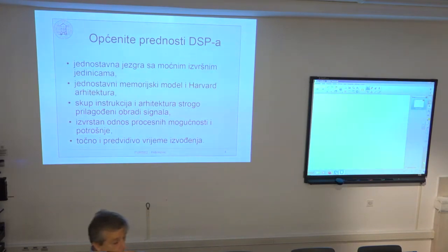And that is very important because if you have to implement some kind of real-time algorithm, then processing of one input sample must be done completely before the next sample occurs. You cannot spend any more time, otherwise the next sample would be discarded. This kind of real-time requirements is very critical, and for that reason the predictability, the repeatability of the execution time is very important.